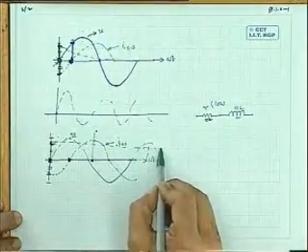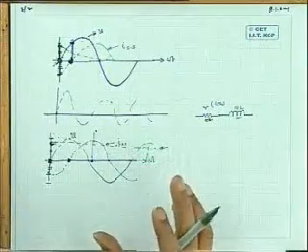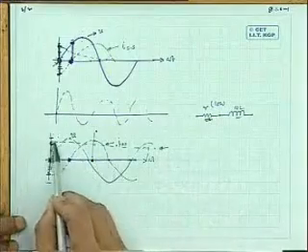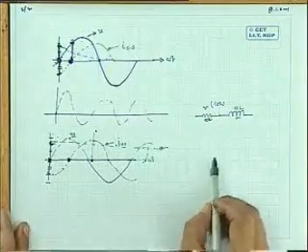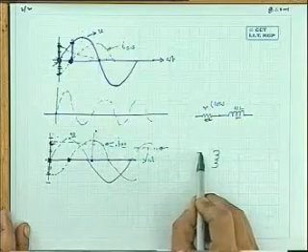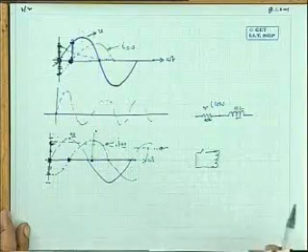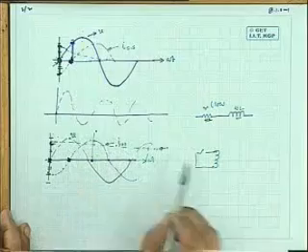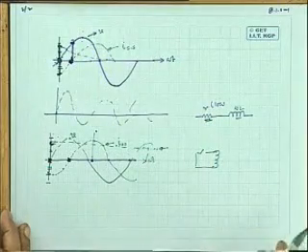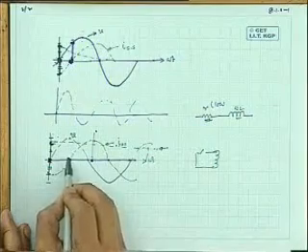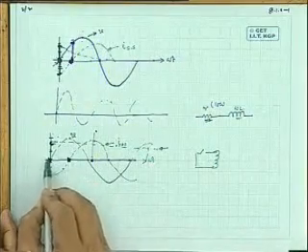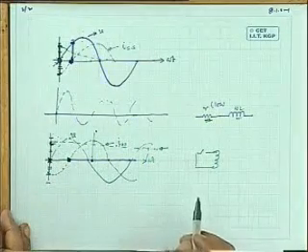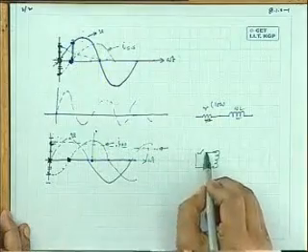But let us not go into those power system aspects, but I just want to point out one should have a fair idea of what he is doing with a circuit when he closes the switch. And also this thing happens when you switch on a very inductive load from an AC source. If you are lucky that you have closed the switch here, there will be no doubling effect. Circuit will straight away go to the steady state condition. But if you are an unlucky fellow, it may so happen that you have closed the switch right at that point. Then doubling effect will take place.